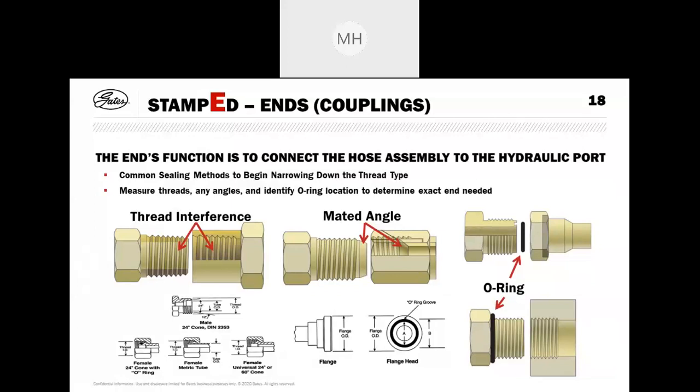I've also included another couple on there, which we do see here quite extensively now. We'll go for the middle bottom, which is the flange style, which obviously is quite common on a lot of machinery. Obviously, here, low pressure and high pressure aspects of this, you have different flange names. So you have a code 61, a code 62, a Caterpillar flange, Komatsu follow some of the code 61 and code 62, but also have their own sizing and particular ranges. Same as Liebherr loaders, they do the same thing.